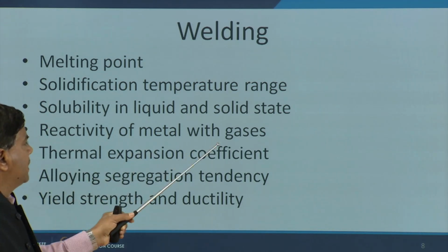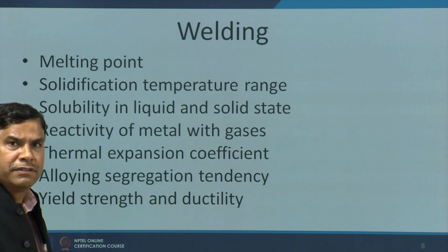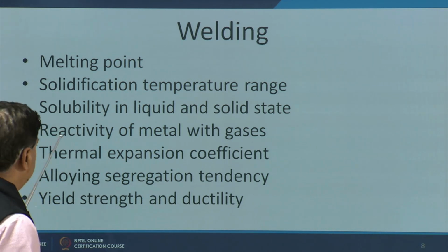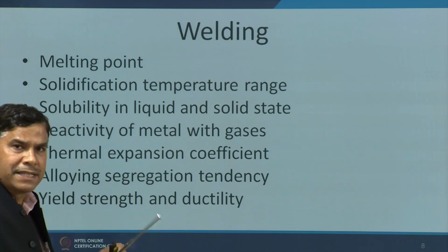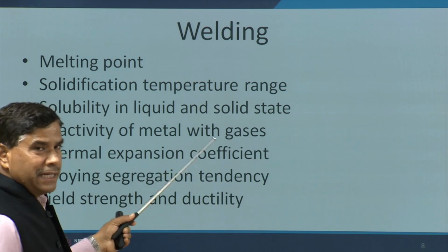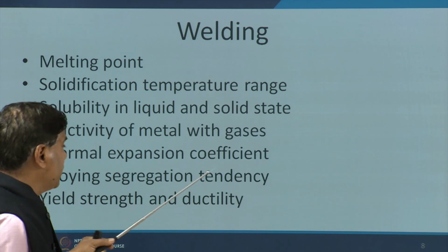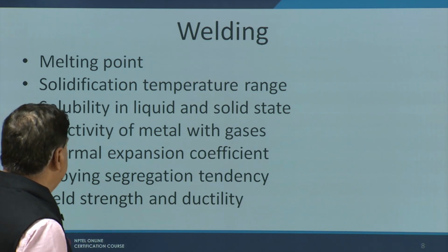Reactivity of the metal with the gases determines the cleanliness of the weld metal, because if the metal is very reactive to the gases all around the weld zone, then it will lead to increased inclusions and impurities in the weld metal.